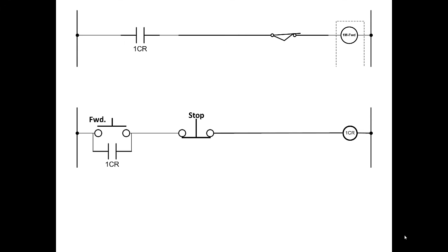Now this means the motor cannot be energized in the forward circuit until the door has been moved away from the switch. So we're going to add a limit switch. We're going to throw that in right now. And this limit switch is there to prevent the motor from continuing to pull the garage door in the forward or up direction after it's reached the end of travel. So when the garage door gets all the way up, it hits this switch, opens the circuit, and it won't travel any further.